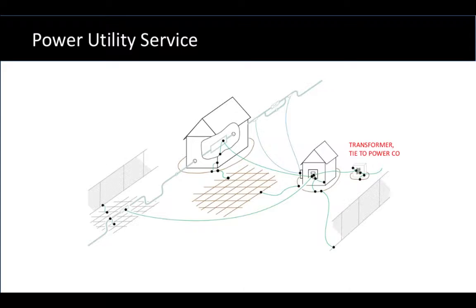There's one last area we need to talk about that can be a bond to grounding systems, and that is a connection to the power company. Now, in our station here that we've been designing all along, we actually, if we've done this right, have not created any inadvertent contacts of the pipeline with cathodic protection to the system or the station grounding system. So we really would not have to address the connection to the utility if we've done all the other things we've talked about. However, let's make this station more complicated.